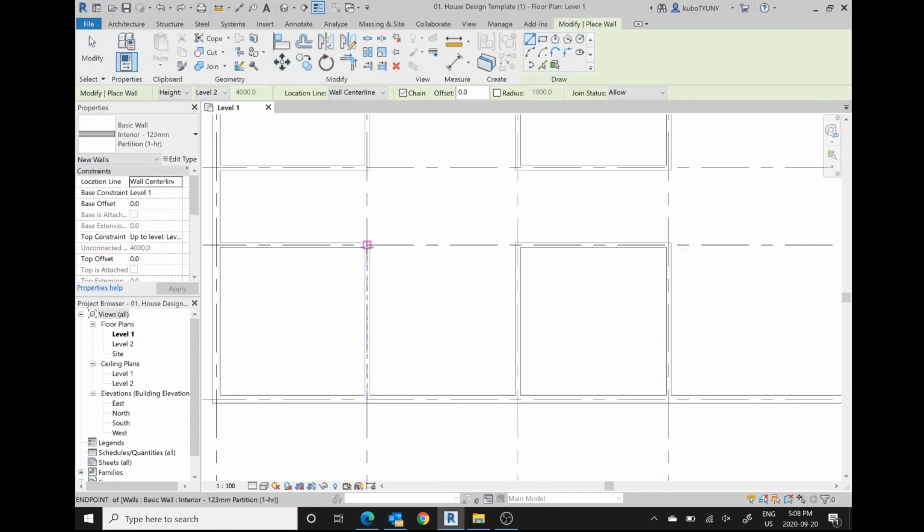Maybe I'll zoom in. What I was going to do is draw a separate wall and move it down by 700 millimeters. But what happened is it automatically connected those walls together. There's a way to break that up and undo it, but it's going to take more clicks than the other method, which would just be to stretch this down till I see 700, click, click, done.